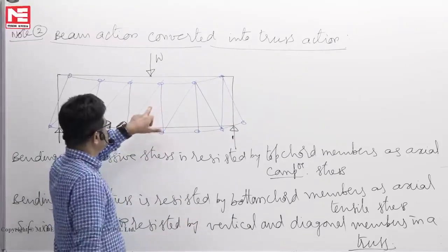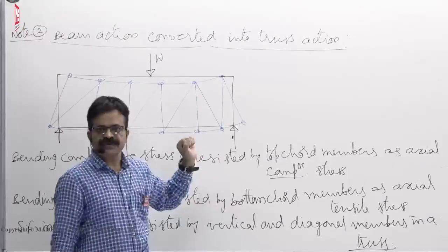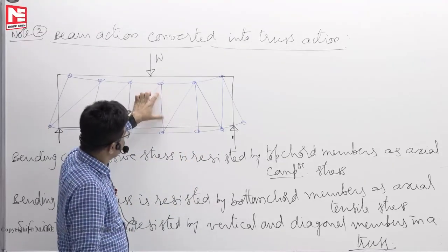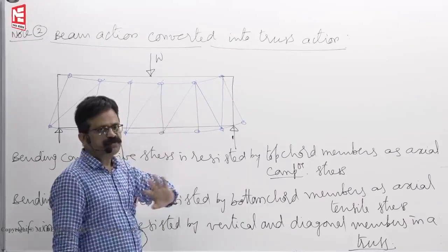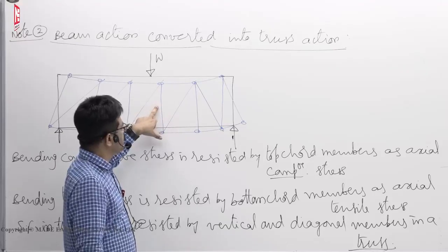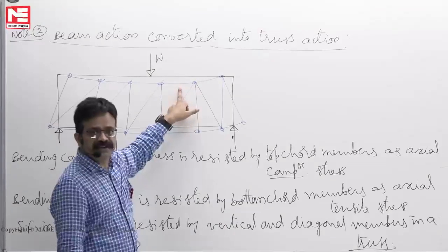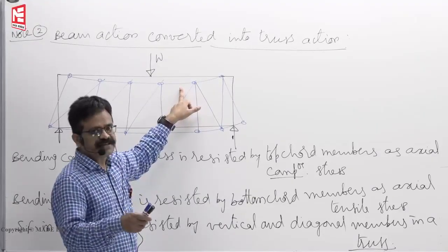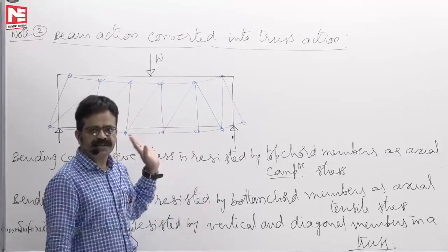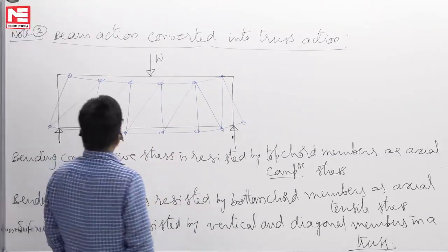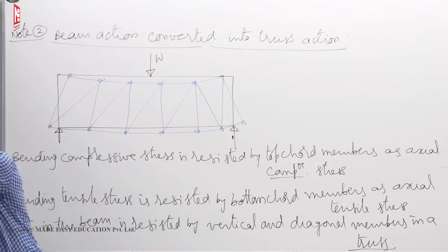Okay, that's why I told you in the earlier class that in a truss, all members are called links only. A link means a straight member connected by pins at the ends, so that it will only take axial force. No bending moment is possible on these members as long as you apply loads only at the joints. If you apply load at an intermediate location between the joints, then the member will bend. We cannot call it stress, and you cannot do stress analysis. So with this understanding, now let us see how to find members having zero force.